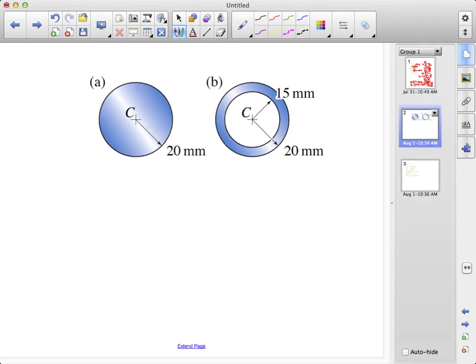So what we'll do here is position our coordinate system here. And now think about the definition of J as this integral over the area of r tilde squared dA. Because of the circular symmetry of this, the most natural differential element for us to take is an annular element of differential thickness dr.